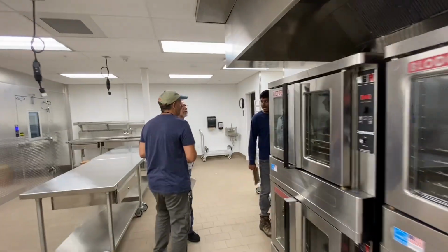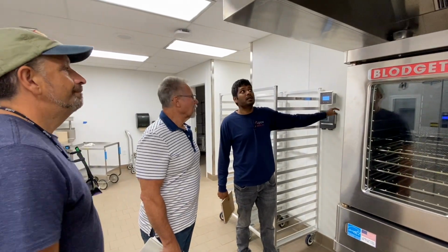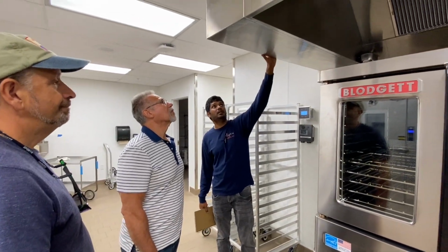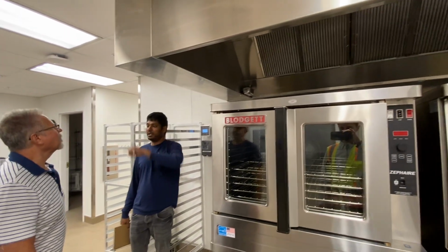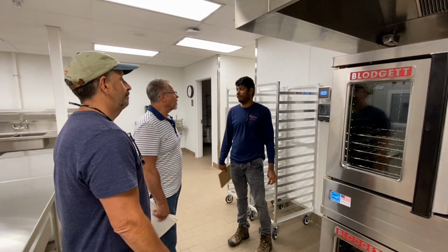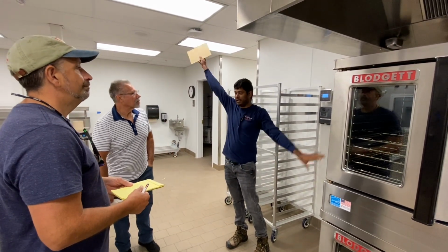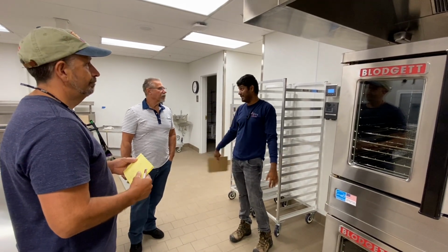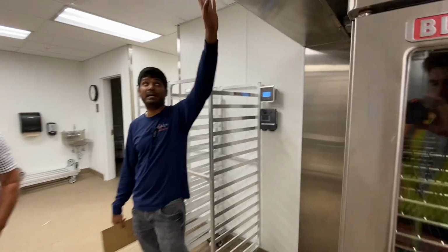If they turn the hood on from this display, they have the hood panel here. This gives the command to the makeup air unit, and it turns the unit on and also controls the speed of the fan. So this just exhausts, and that supplies. During a life safety event they trip both and everything shuts down. But the exhaust fan turns on.